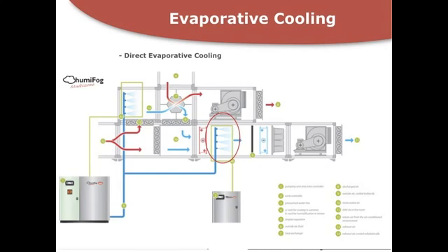The control strategy allows for the management of direct evaporative cooling, which sprays water straight into the supply flow, by making sure that the supply conditions are well within the permissible limits, and manages the indirect evaporative cooling, which instead sprays water on the return airflow.